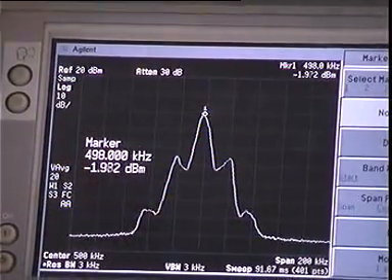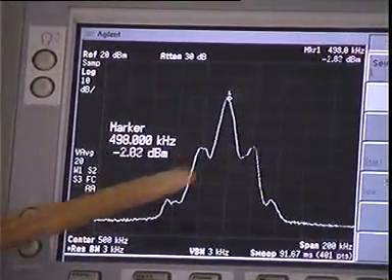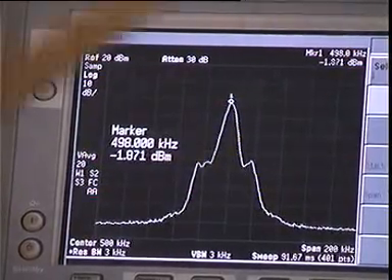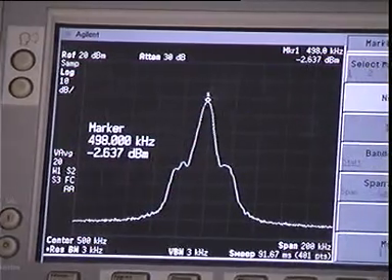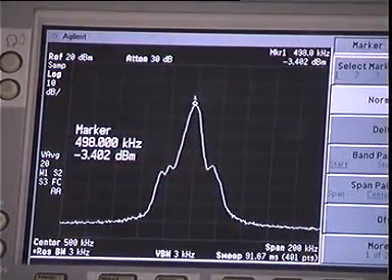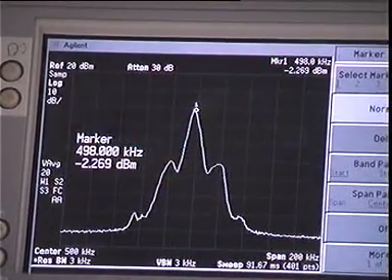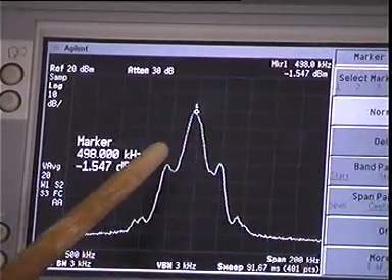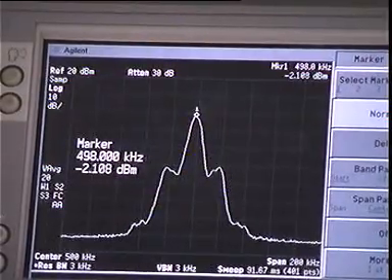If I reduce the message signal amplitude a little bit, then these two sidebands should disappear. They are almost not there. So in this situation, this is similar to amplitude modulation. This is the case of a narrowband FM, similar to having upper sideband, lower sideband and the carrier. This happens when the beta value is very small.